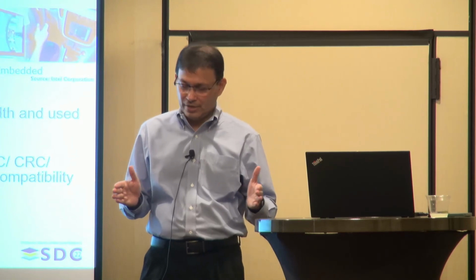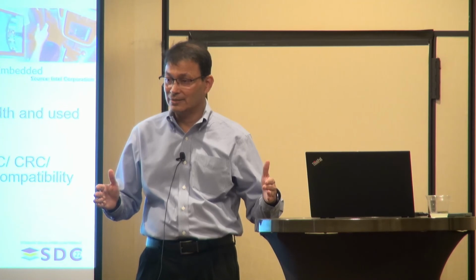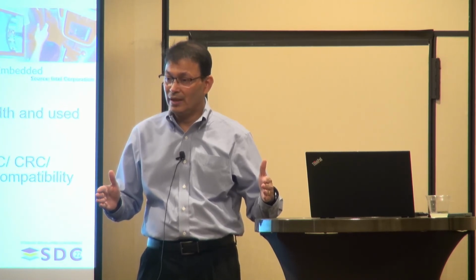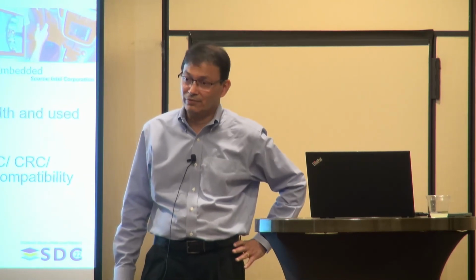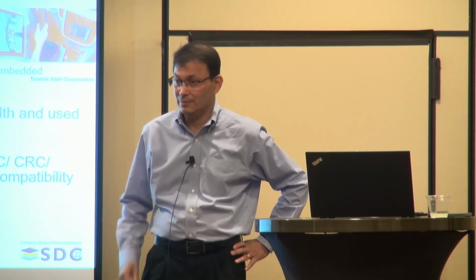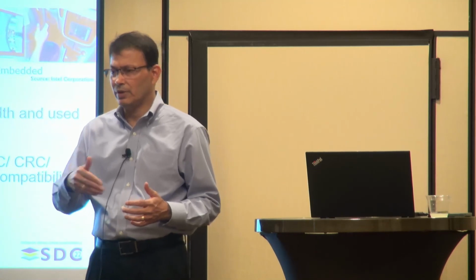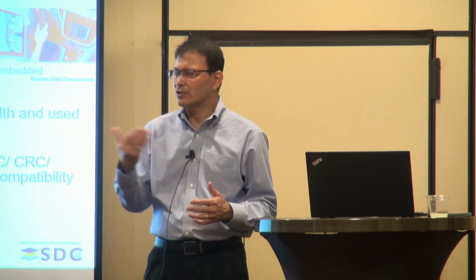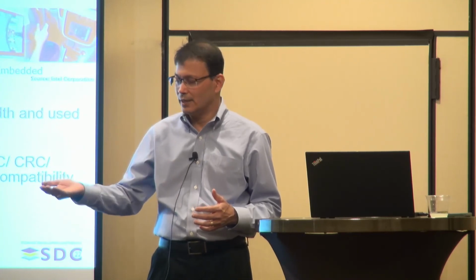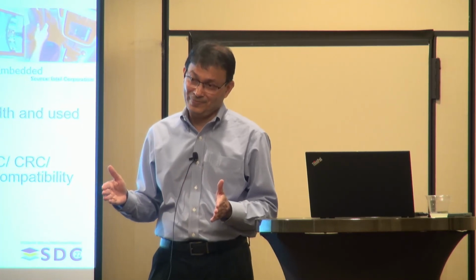You can say, if I take an average over the last 10 microseconds, let's say, and I see that I'm consistently using the link less than 25% of the bandwidth that is available, maybe I go to a by 4. Especially for NVMe, you don't have to move back and forth that fast. We also have mechanisms where the other side will tell you how quickly can I go from a by 4 to, let's say, a by 8, realistically.